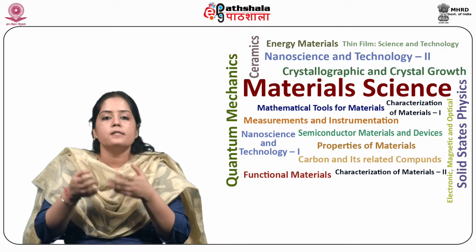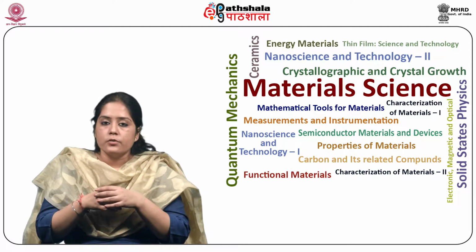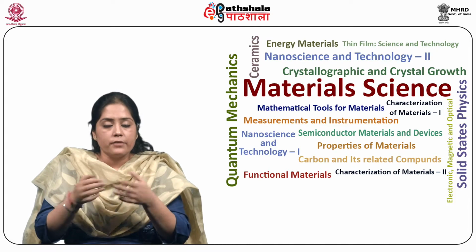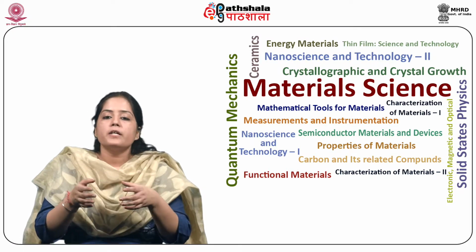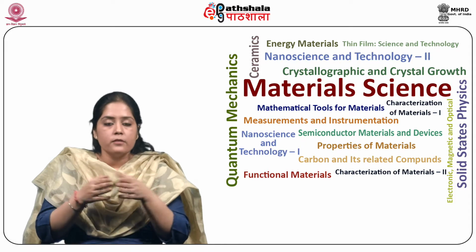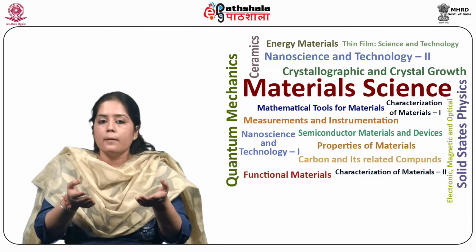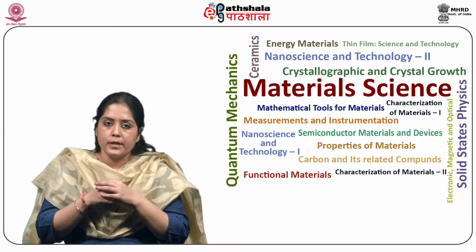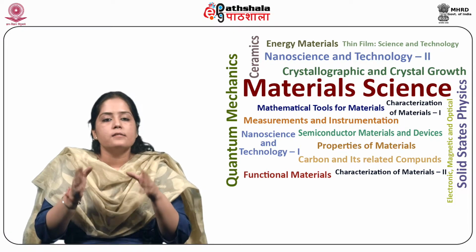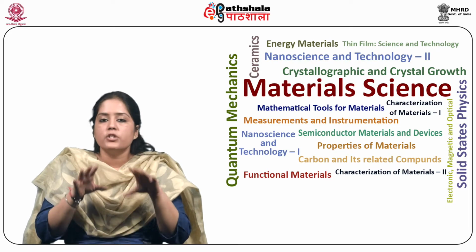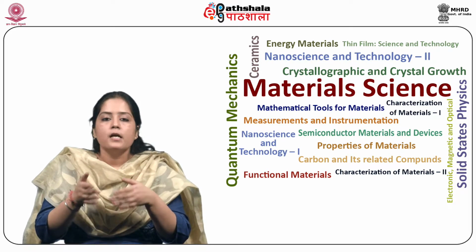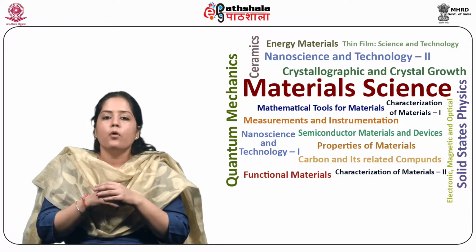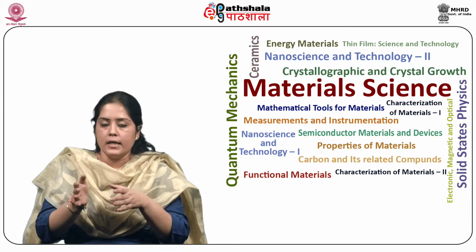So, numerous optical methods are available for the realization of optical sensors, such as ellipsometry, spectroscopy, luminescence, phosphorescence, fluorescence, Raman, interferometry, white light interferometry, modal interferometry in optical waveguide structures, spectroscopy of guided modes in optical waveguides, grating coupler, resonant mirror, and surface plasmon resonance, SPR. In all these sensors, the detection relies on measuring the change in refractive index, absorbance and fluorescence properties of the sensing material or molecules in response to the analyte.